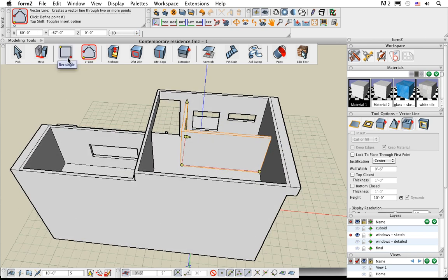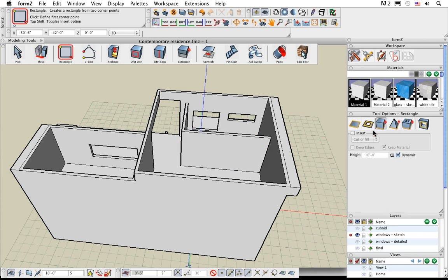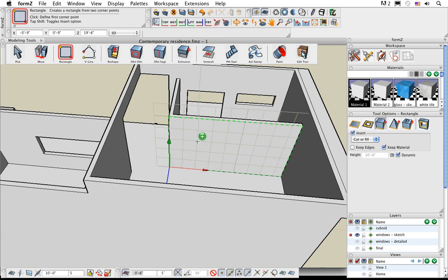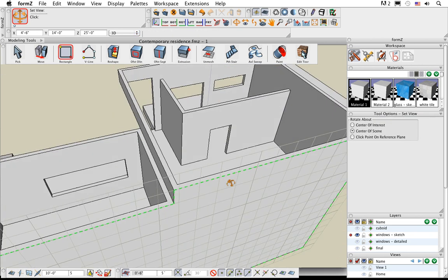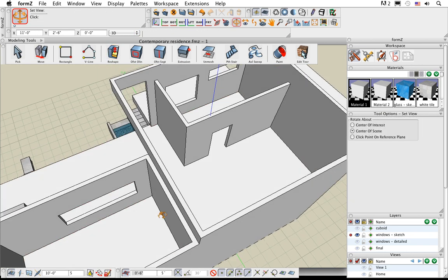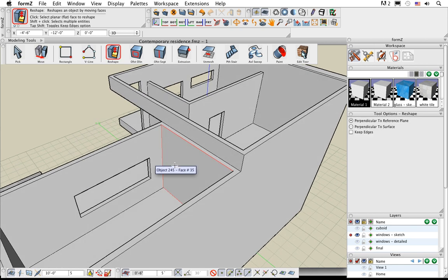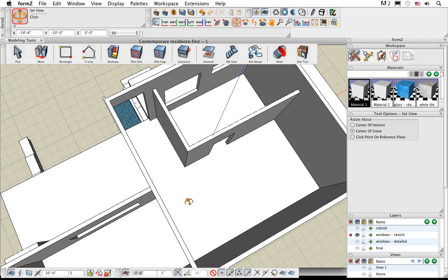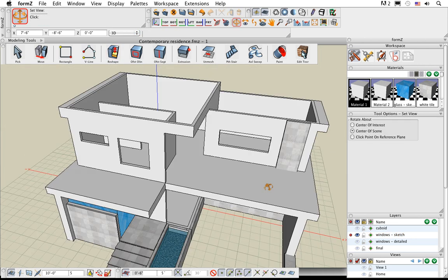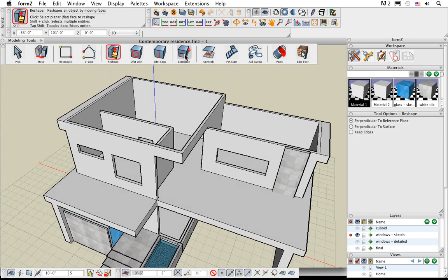If we want to insert a door, there's window and door components that you can just click right on the wall and it automatically punches a hole there for you, places a door for you. But if you just want to conceptualize this, you can just use the drawing tools also. Just draw a shape with the insert option, push it through to subtract that part of the wall. We have a double wall here because of the way we sculpted out those inside parts of our rooms, so we can reshape that all the way through to subtract that, or snap it to the edge to make that a single thick wall. I think you get the idea of how we can do that. Let's define the roof. Once again, we use our 3D derivative tool, and I want to derive from whatever's highlighted.